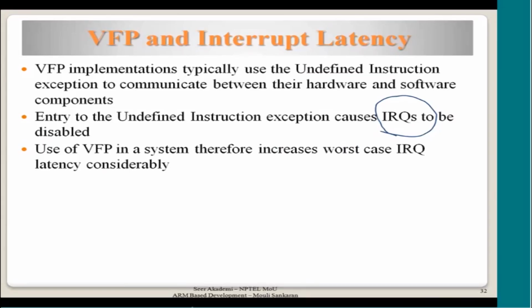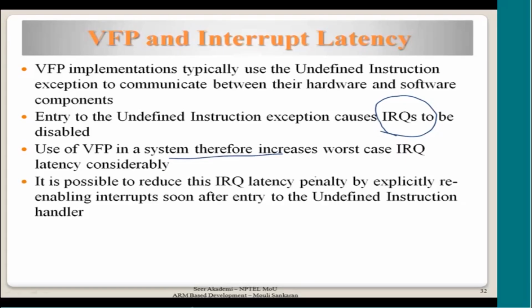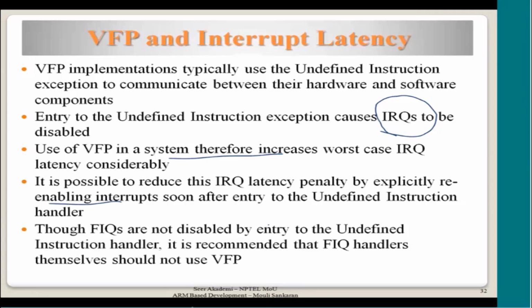So use of VFP in a system therefore increases worst case IRQ latency considerably. It is possible to reduce this IRQ latency penalty by explicitly re-enabling interrupts. We have to re-enable the interrupts inside the handler to make sure that the interrupt latency is reduced.